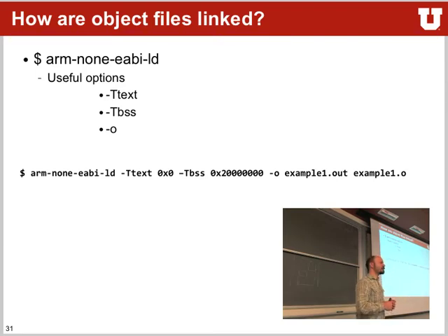So the linker would probably oblige and actually do this for you. But the problem is that in reality, your physical hardware will probably not accept this file, or it would just not execute, or nothing would happen at all. The 2000 here is very specific to the ARM Cortex that we are using. At 2000 is where the RAM sits, where you can store variables and have very quick access to them. It's very, very fast. While address 0, remember, is where we have to store our initial stack pointer and the jump address. That's usually where the code is sitting.